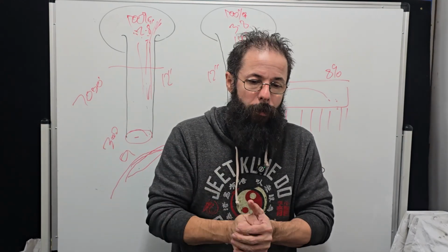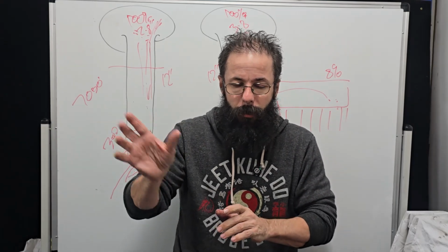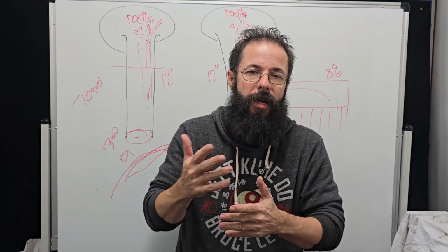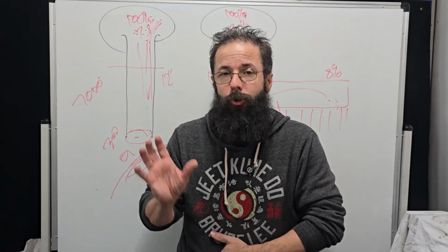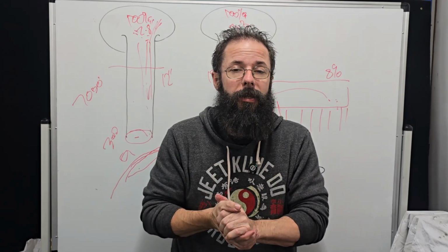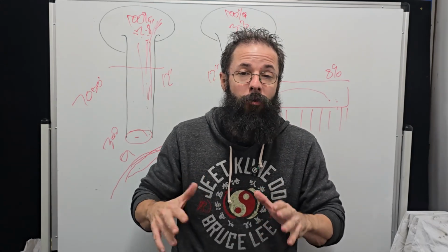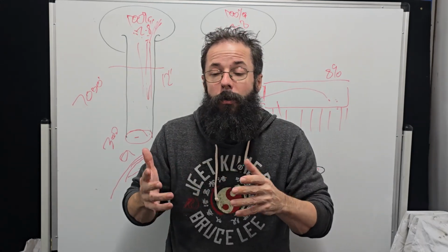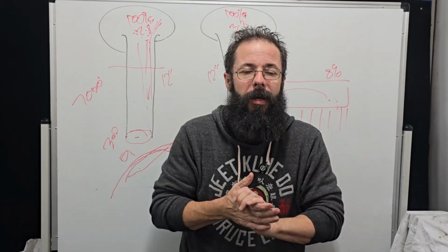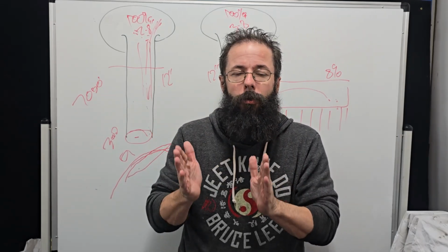But what it told them straight away is that when they dented it, I think they ended up making more horsepower. I had a quick look at it, and that told me it increased velocity. So velocity was never targeted properly, meaning the pipes are actually too big. Hence the dent helped them increase velocity, improve that scavenging mechanism, and that's why it made horsepower. It wasn't that the dent didn't matter. It was the pipes were never right to start with. So we've got to be really, really careful what we take as gospel out there. Again, I don't know it all, and there's guys out there far smarter than me, but we've got to think about the mechanisms that we're playing with and why we got the results we did.